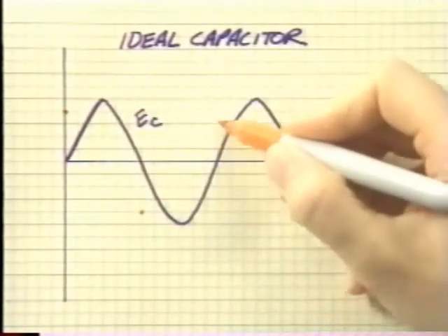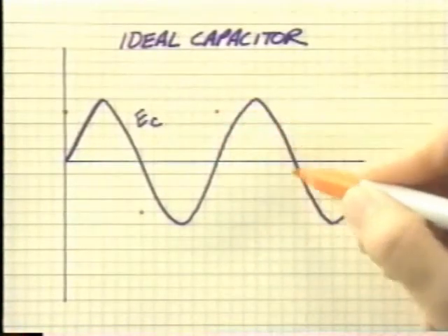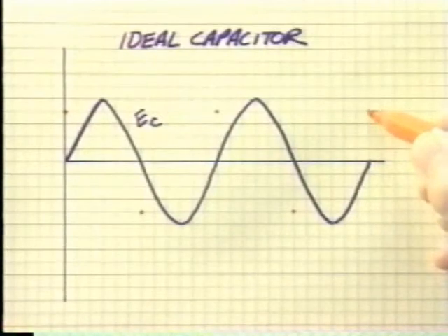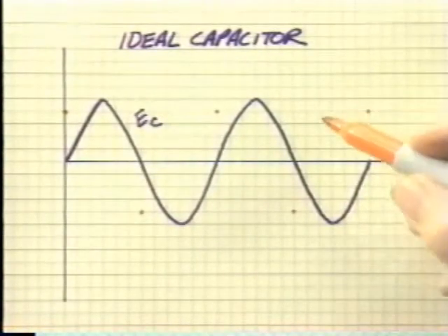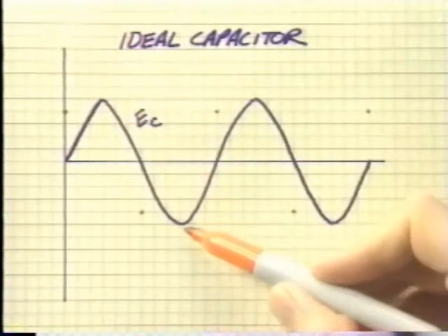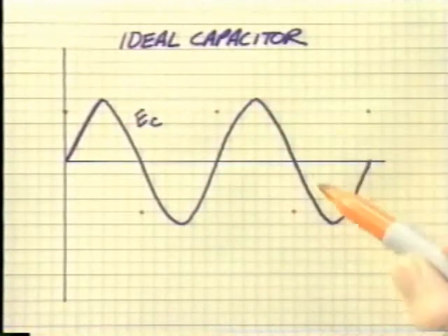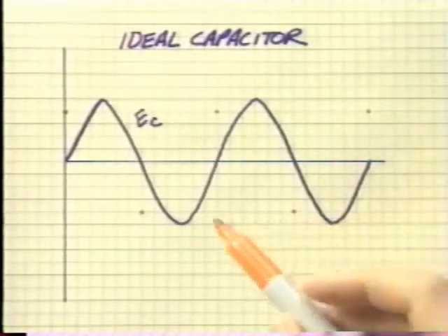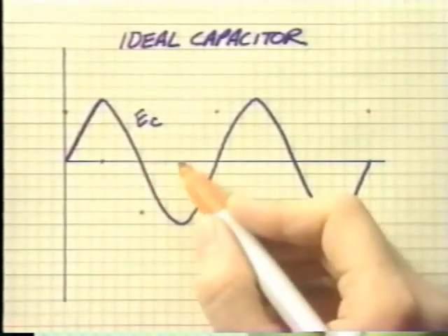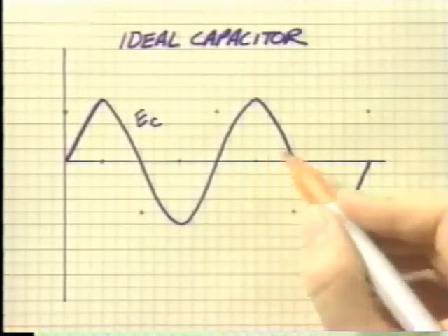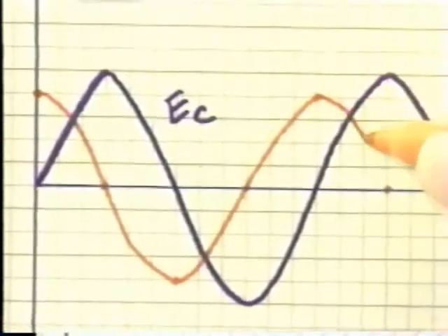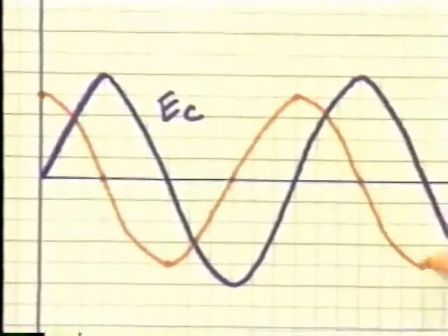A different amplitude has been arbitrarily selected for the sake of visual clarity. Since the least rate of change in a sine wave occurs when the voltage is at its maximum positive and negative values, then the minimum capacitive current will take place at these points. These are also marked by dots. These concepts can be depicted graphically as shown here.